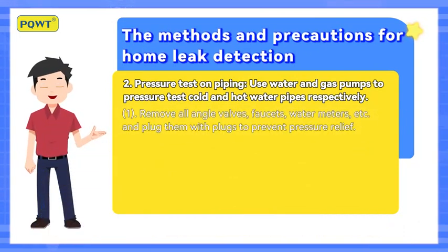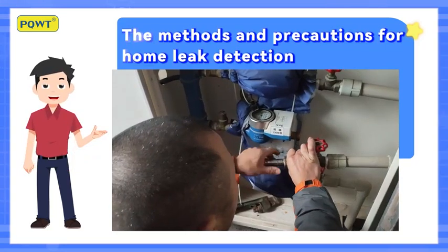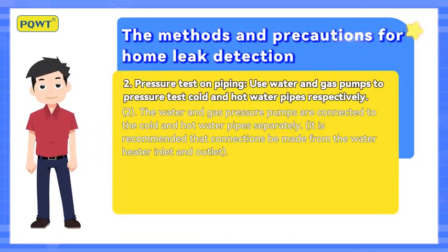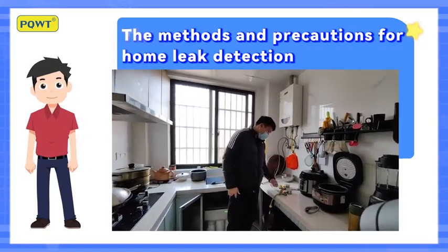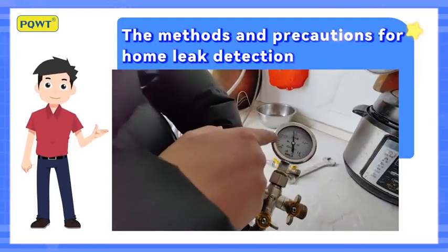1. Remove all angle valves, faucets, water meters, etc., and plug them with plugs to prevent pressure relief. 2. The water and gas pressure pumps are connected to the cold and hot water pipes separately. It is recommended that connections be made from the water heater inlet and outlet.